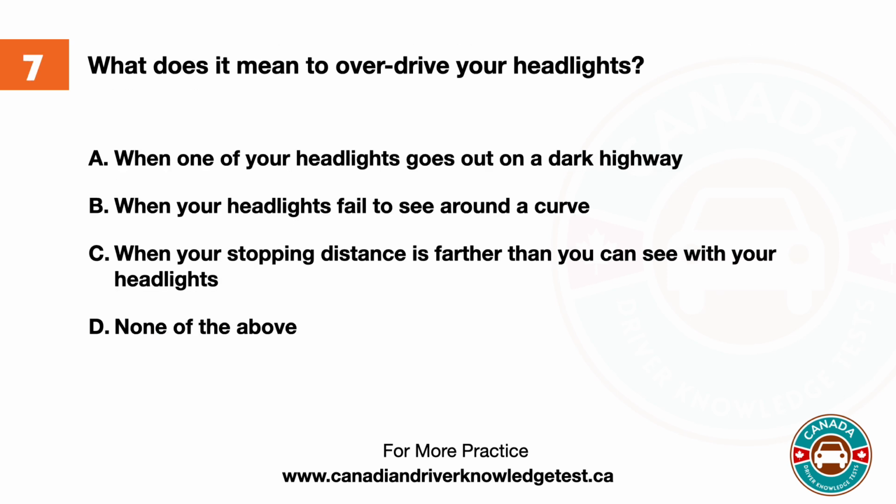Question 7. What does it mean to overdrive your headlights? A. When one of your headlights goes out on a dark highway. B. When your headlights fail to see around a curve. C. When your stopping distance is farther than you can see with your headlights. D. None of the above. The answer is C. When your stopping distance is farther than you can see with your headlights.